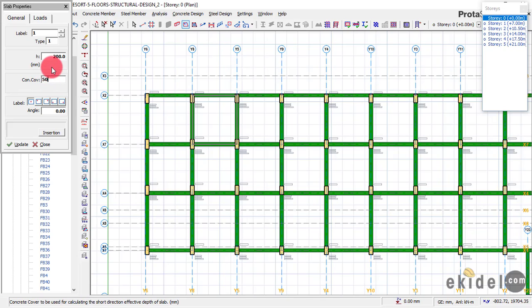Depending on the kind of design code you're using, we are using Eurocode for the design of this structure. So I want to use 50 for my concrete cover. Again, we also go to the load here. Since you have already done the superstructure loading, as we used 1.5 for the dead load and 1.5 for the live load, you don't have to touch the load again. Leave the load as it is as of the